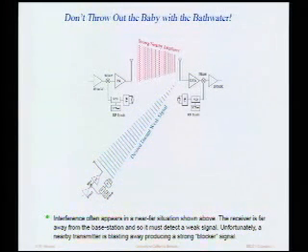Unfortunately, you're in a cafe and right across from you someone's also talking on their cell phone. Not only are they talking loud and annoying, but their power amplifier is quite annoying too, because it's transmitting a lot of power, and the frequency could be very close to the frequency that you're receiving. This is called a near-far situation. You're near an interferer and far away from the desired signal. This means your receiver has to deal equally well with small signals, which are very close to the noise, and large signals, which excite nonlinearities in your receiver. That's the key word, nonlinearities, and we'll talk quite a bit about this in this course.